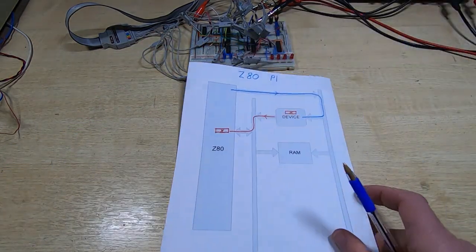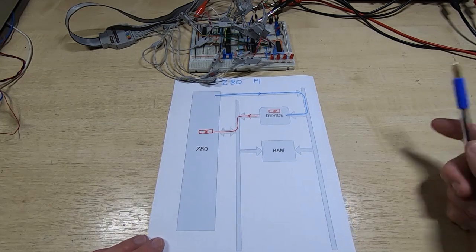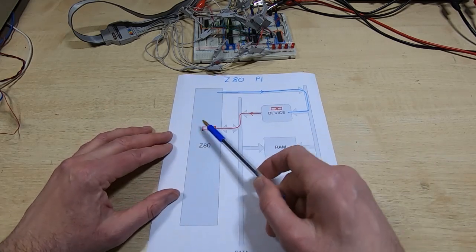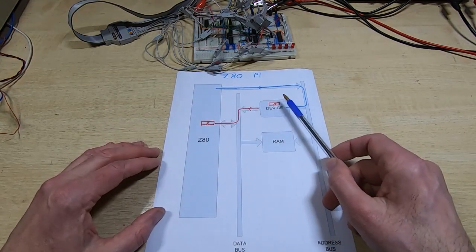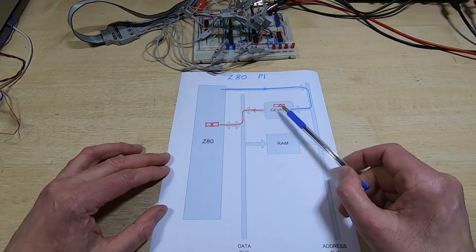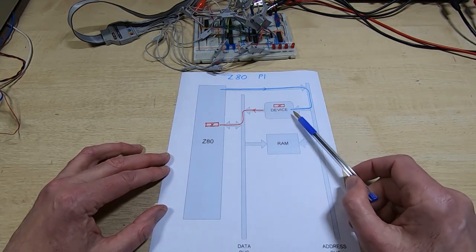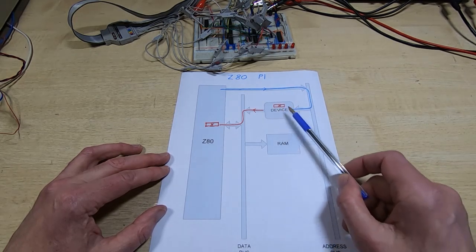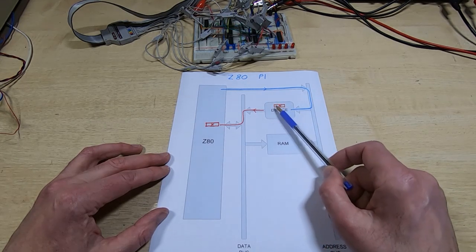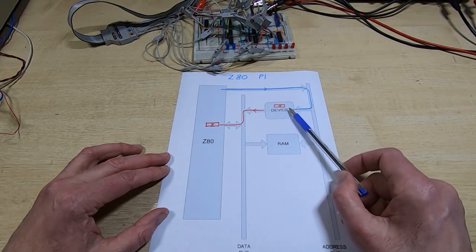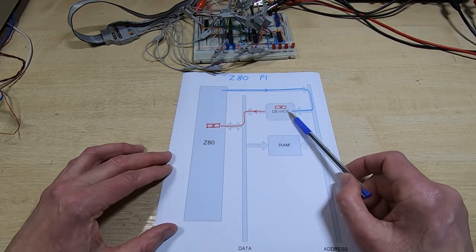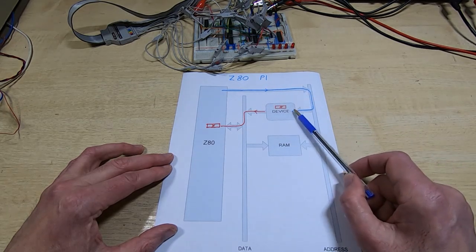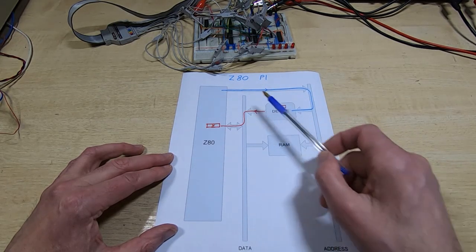Normally when a Z80 processor wants to transfer data, it typically does it in two phases. So the first phase, if we look at this diagram, very simple, oversimplified, but for argument's sake, let's say we have a device, so it might be our floppy drive system, and we have a value we want to transfer into RAM. The first thing the Z80 does is it performs a read. It might be a memory read, or it might be an in-out read, and it supplies an address to the device, so the device can be selected within the system.